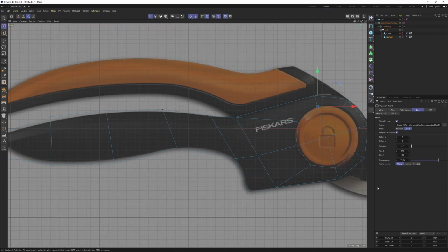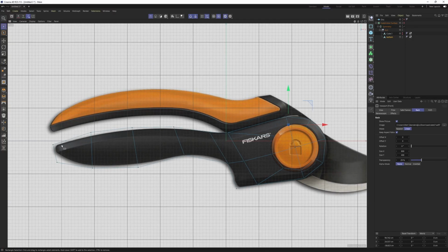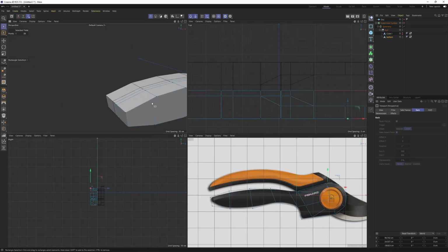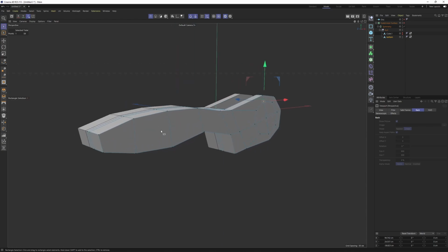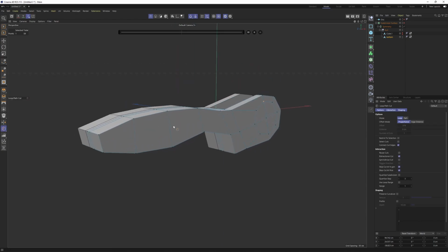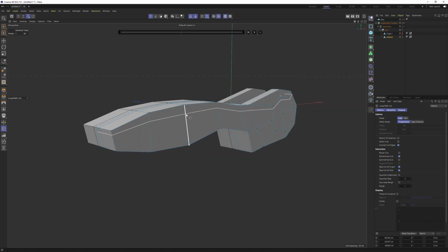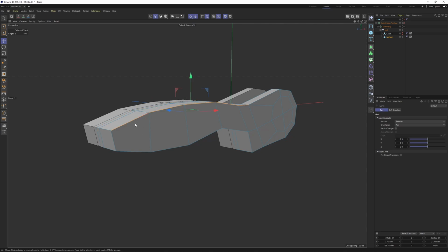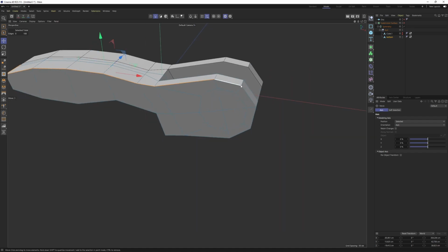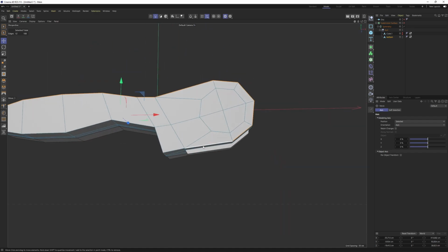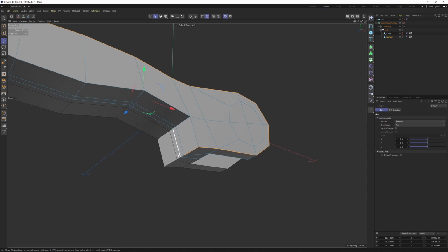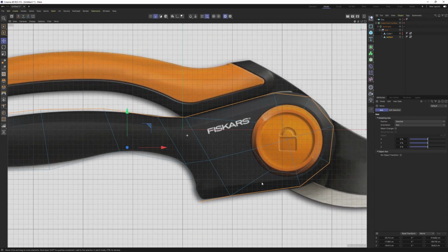Now, if I lower the transparency, you are gonna see that we have the bevel, these polygons. So if I want to get this by loop cut, probably I will not get what I want. So you can see it. So the second option is to select these edges, and let me turn off that snap. Select these edges manually. So these are the ones that should be beveled.